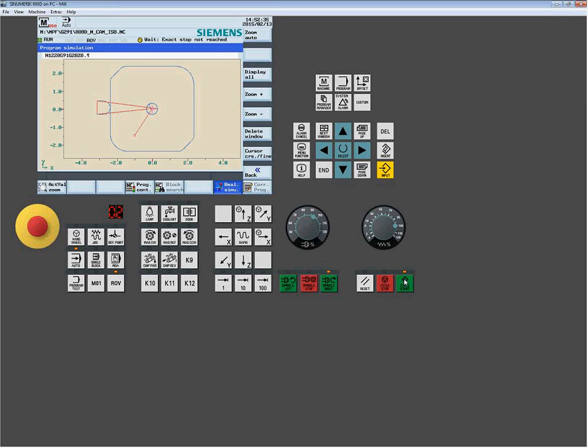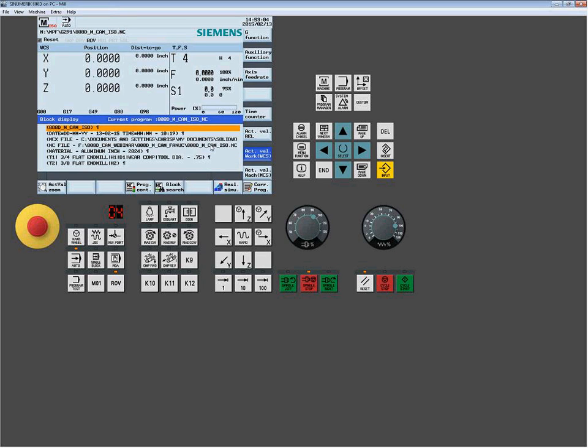What I probably recommend, if you're going to try to leverage the machine in this mode, you're probably going to find you want to do most of your setups, where you have all those extra tools, the measure tools and all that available to you, which are great features. You're probably going to want to do all the setups while still sitting in our standard G290 mode or Siemens mode, and then just simply switch to ISO mode when you're ready to physically run the program. Okay. So that's a quick overview of the ISO mode.